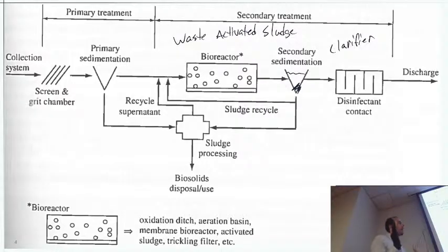Okay, so that's kind of secondary treatment, and you'll notice another component here for both of these is to capture the sludge and whatever particles, and we will usually collect those, and well, we always collect them and then process them in some way, and that's an opportunity that we could generate fertilizer. If we treat it properly, we can create biosolids that may be able to be used for a kind of beneficial reuse. It's also possible that we just landfill it, and so we'll just be filling up trucks. So we'll have to take this sludge, dewater it, and then send it along, is typically the process.